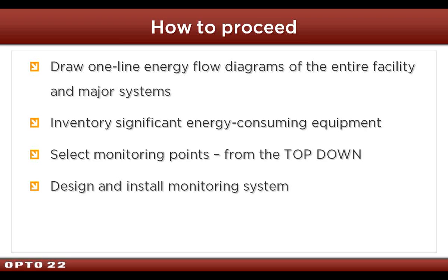And I used what I always called the top-down approach, and that is the meters. Every single dollar that you spend goes through a meter. So by just picking up the meters alone, you can get a huge amount of data because you can see how the facility varies depending on the day of the week, the time of day, the shift, the weather. So the meters are the absolute most important point.